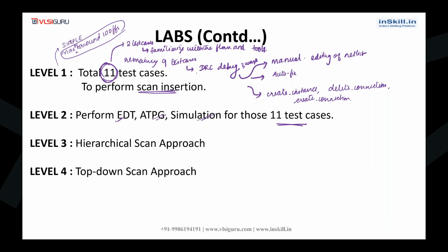In ATPG, we will be performing ATPG for these fault models: the stuck-at fault model, the transition delay fault model, and the IDDQ fault model. The path delay fault model will be covered only theoretically.